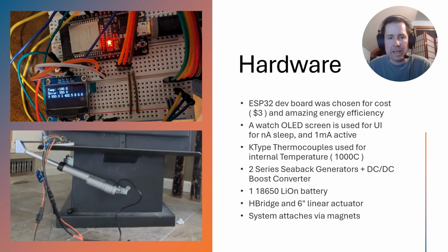As my goal here is a passive device, one that harvests its own energy, all the hardware was selected to minimize the current draw while idle. The ESP32 SoC I chose is a unique dual-core device, with one high-performance CPU with a selectable clock cycle, and one real-time clock processor with the ability to run on nanoamps of current. While in deep sleep, the RTC can capture hardware interrupts and generate software interrupt timers for the main processor. This will be critical for writing the firmware.